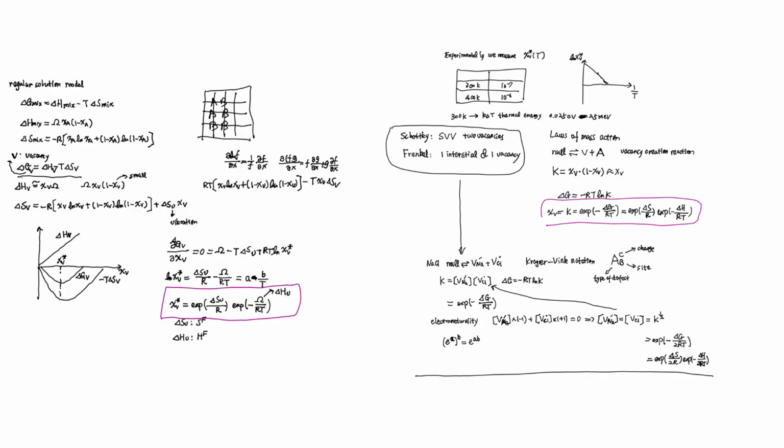So you already have the data at different temperatures. We have a column. Okay, so we have 300 Kelvin, 10⁻⁷, 400 Kelvin, 10⁻⁶, something like that. Keep going. And we know it has this dependence in terms of temperature. How do we get delta SV and how do we get omega, or delta HV?